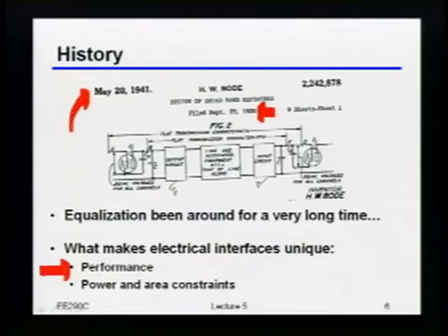The other thing is that not only do you have to achieve that very high throughput, but you have to do it within very, very tight power and area constraints. So this is saying something like, I want that 20 gigabits per second, but I want it in the size of a couple of pads and in like 10 or 20 milliwatts, right? That very tightly constrains what techniques you can apply, or really it forces you to be creative in how you build things, because you can't just attack it by brute force and meet the constraints you're interested in.